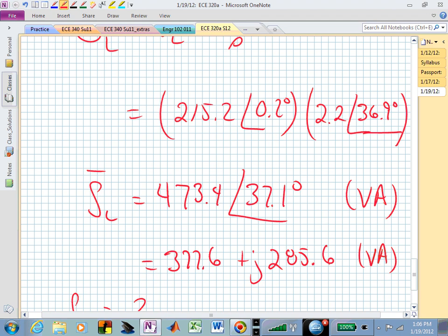There's all sorts of ways to find this, actually. You can look at the difference between the voltage angle and the current angle of the load element, which is two pieces. It's the R plus jX, which is really the angle of that impedance. That's the difference between the voltage and the current, is the angle of the impedance.